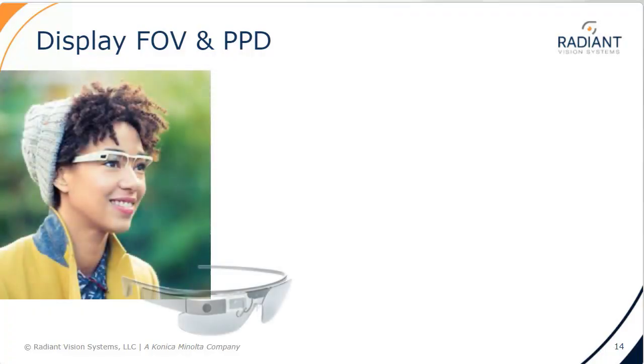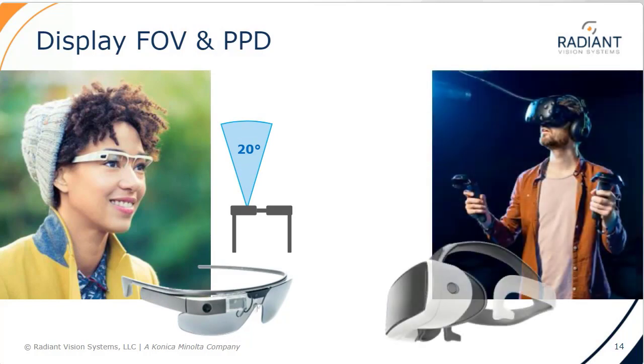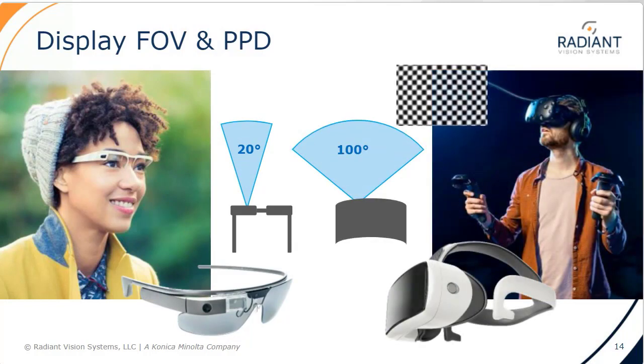For instance, each XR device differs in form and function to meet particular application goals. A pair of AR smart glasses intended for daily use have reduced hardware size and weight, which typically means smaller components that limit the display field of view. On the other hand, a VR headset intended for gaming may be designed to maximize field of view and boost visualization performance with high-resolution displays and adaptive focal points, such as foveated optics.